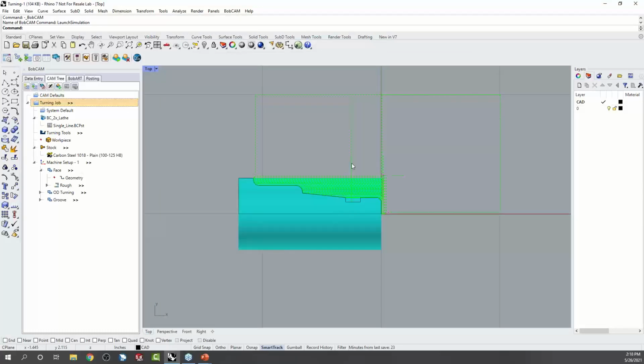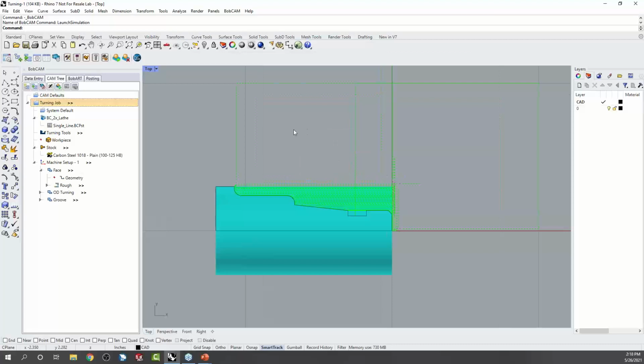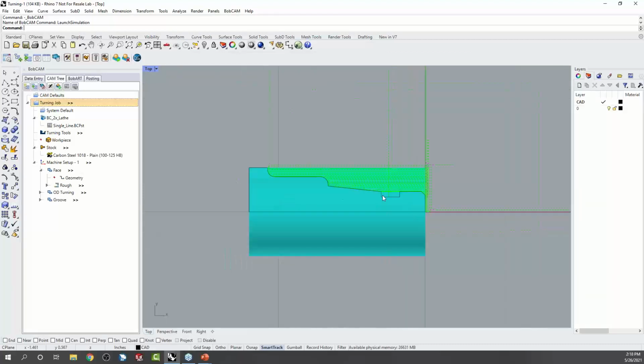All right. Now, when it comes to turning, there are a lot of different features within the turning software that I think are really important to pay attention to. One of them has to do with our operations stock. As we process operations, we have a recording of the steps or the material that's been removed. And what you can do is use operation stock as a boundary to better target where material is left over. We pre-calculate one based on the previous operation, but you could also select your own profiles in order to tell the software where material is.